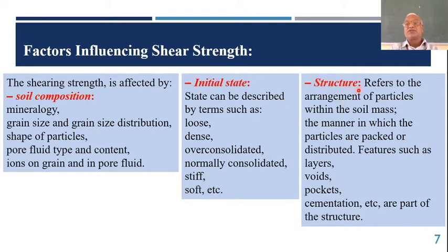Next is structure of the soil. It refers to the arrangement of the particles within the soil mass, the manner in which the particles are packed or distributed. Features such as layering, voids more or less, pockets big or small, cementation tight or loose, etc. are part of the structure. So the factors which will influence the shear strength are all these.